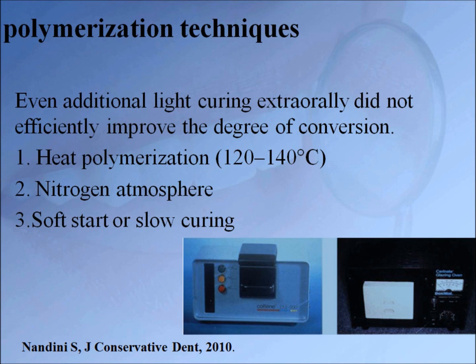Post-curing heating of resin composite material decreases the levels of unreacted monomer after the initial light cure stages. Basically, two mechanisms can be involved in this phenomenon. First, the residual monomer will be bonded to the polymer network as a result of heat treatment, leading to an increase in conversion itself.